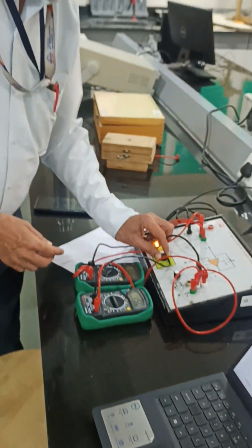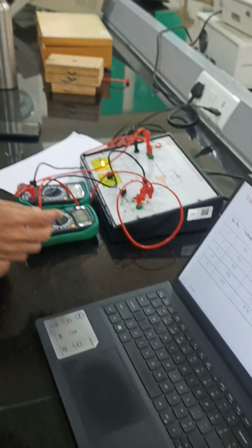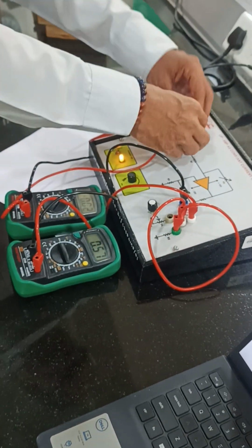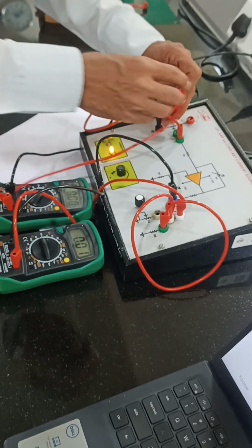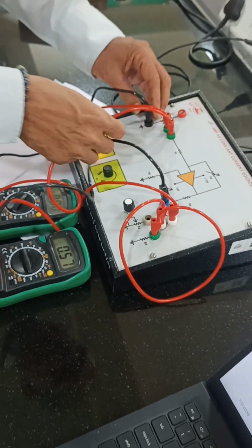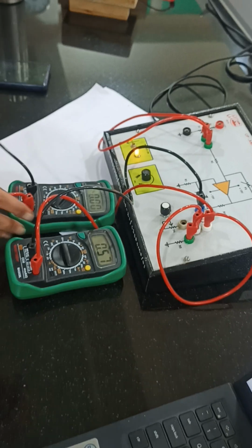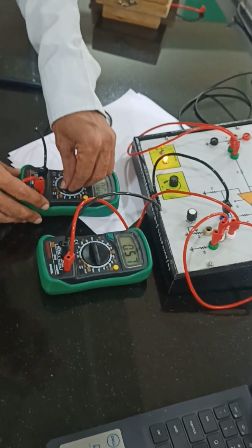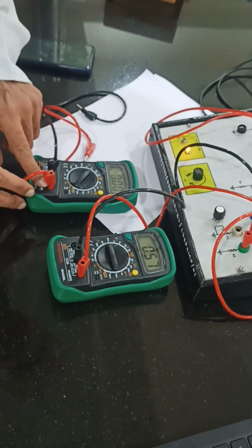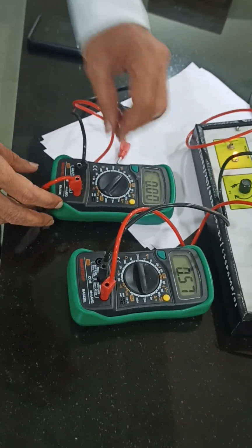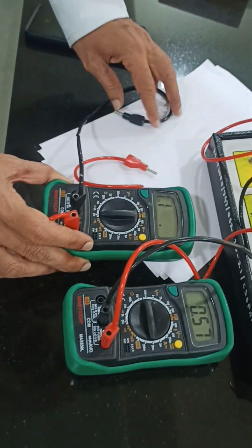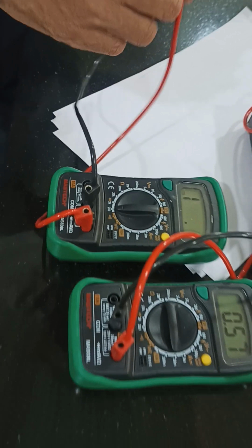Now let us see how this current can be kept constant by using OpAmp. So for that the circuit will be like this. Remove this voltmeter now, it is not needed, and use this multimeter as an ohm meter for measuring the resistance. The terminals will not change, and then you have to place the dial on 200 ohms resistance.